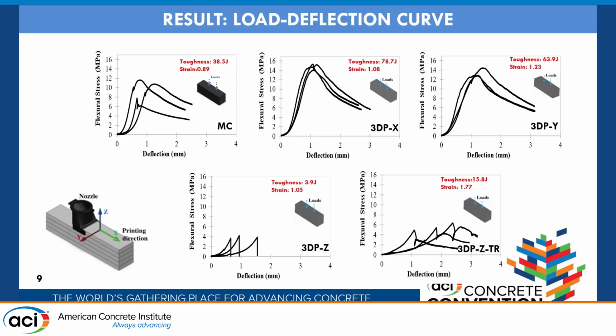And so just to present the load deflection curve for these tested specimens, for the mold cast samples, of course, we see the nonlinear relationship between the stress and also the deflection. And for these, beyond the maximum stress, we see that the specimen starts to fail in a strain softening behavior.